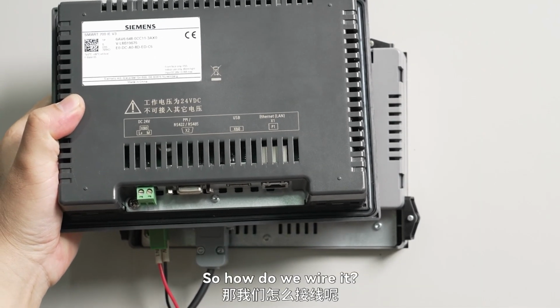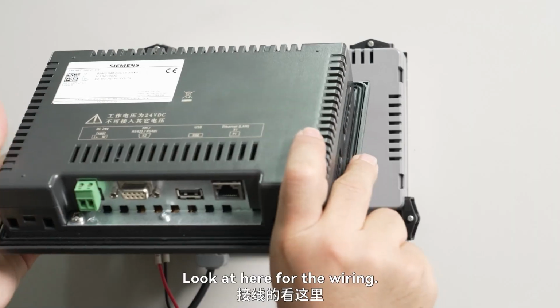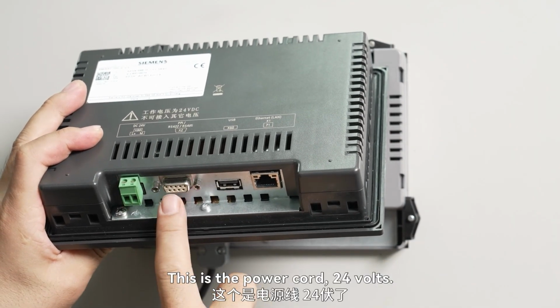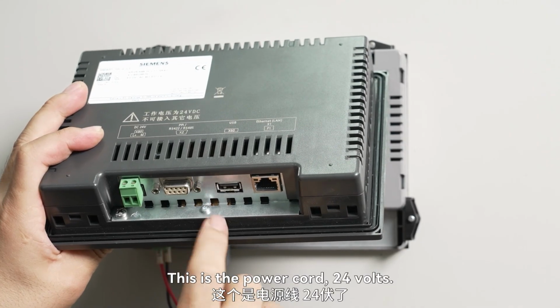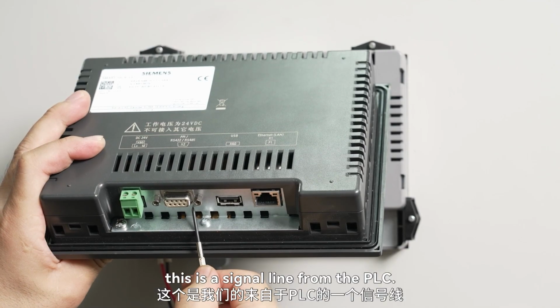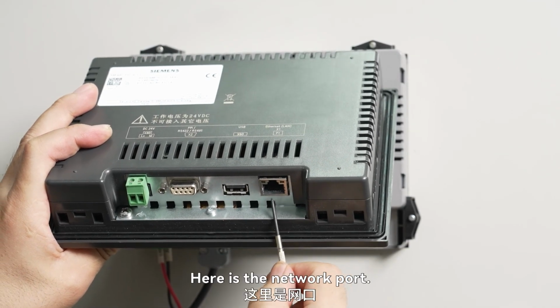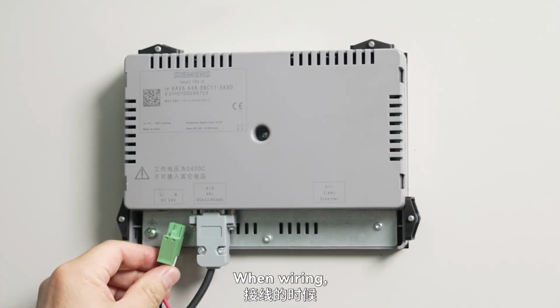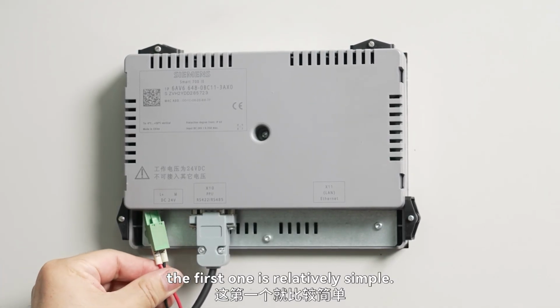So how do we wire it? Look at here for the wiring. There are 3 interfaces here. This is the power cord, 24 volts. The second one, here, this is a signal line from the PLC. And the third one, here is the network port. That's all about it. When wiring, the first one is relatively simple.